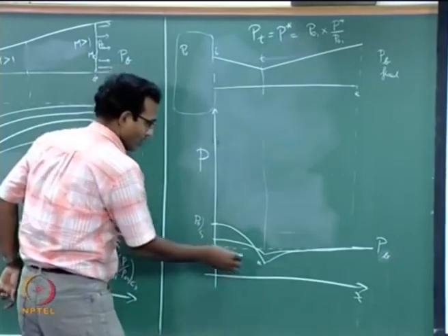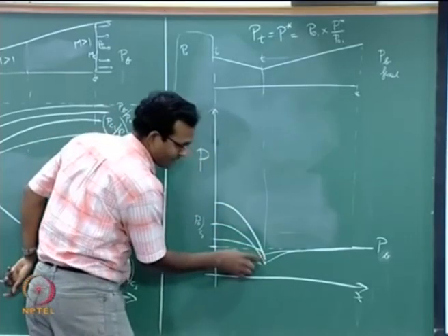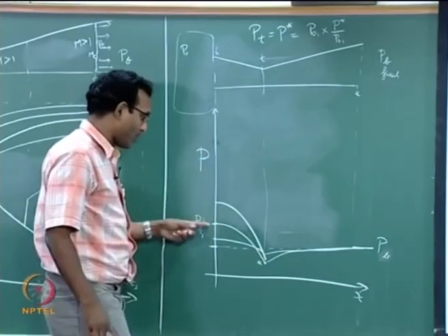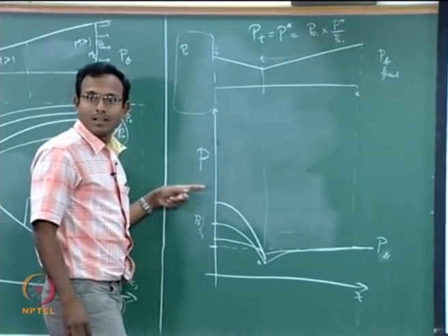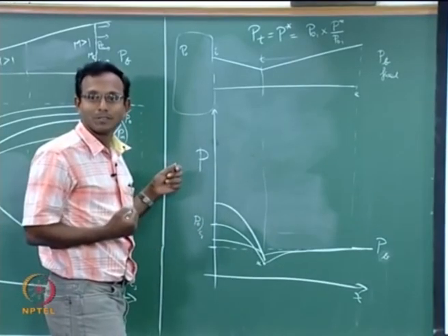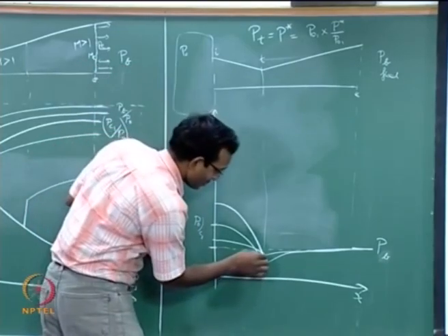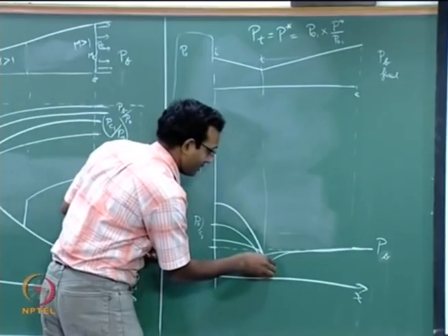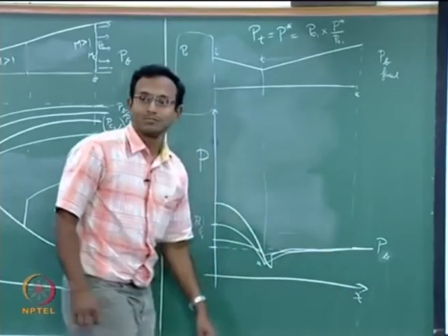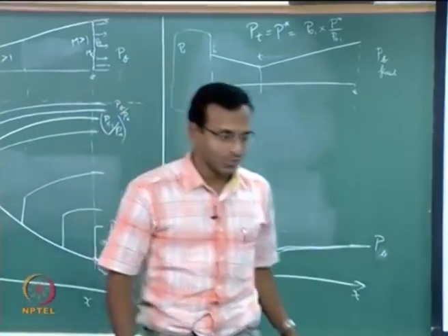Okay. So if this is my critical pressure 1, the next case is going to be higher, and then we know that if I go above pressure critical 1, Pb by P naught will go below my first critical pressure, which means I am going to go supersonic, jump across with a shock and go subsonic. So it is going to go like this, jump across and then go along the subsonic solution to reach that back pressure. Okay. It looks more confusing beyond this point. Let us go to the screen again.